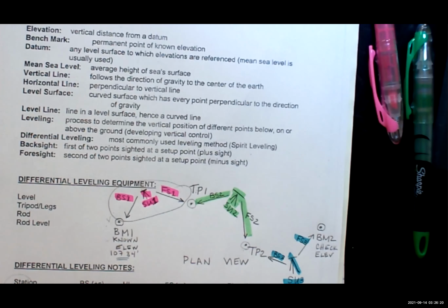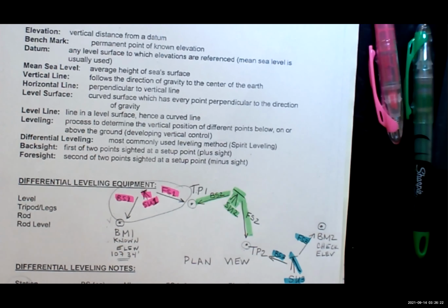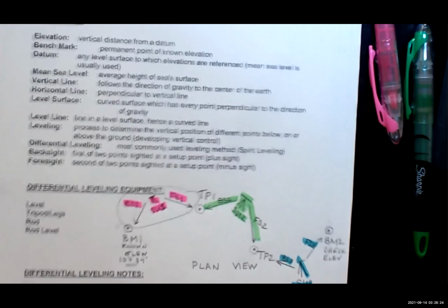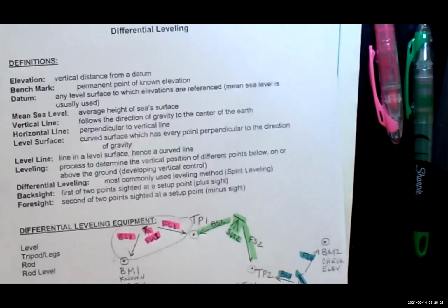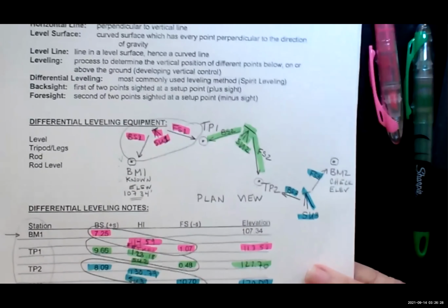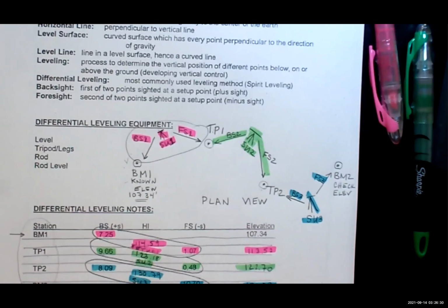And surveying is so much fun because you're outside, it is really great. All right, so in this case, we're going from one place to another. I mentioned the first week of school, I believe, that when they're doing construction at Cabrillo's campus, they'll go off one benchmark and set up a temporary benchmark for the whole time they're doing the construction, right?